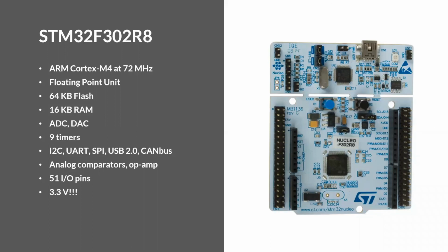The important thing to note about these pins is that they operate at 3.3 volts. Due to the design of silicon in the past, a lot of devices used to operate on 5-volt logic. Even today, you still get a lot of microcontrollers that run on 5 volts, and therefore some peripherals that you might want to connect to your microcontroller operate at 5 volts. You need to make sure that everything is running at 3.3 volts, or you could damage either the microcontroller board or your peripheral.